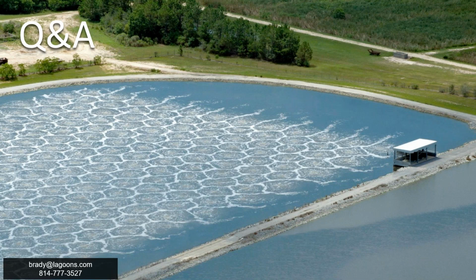Last question that has come in here, looking for a discussion on blowers versus compressors, especially with the use of fine bubble aeration lines. My experience, and we used to use compressors way back when the company started, we used to do very low airflow, and compressors were a good fit because they're relatively inexpensive for producing 4 or 5 SCFM. My experience with compressors, though, is that they're great at pressure and great at being small and inexpensive, but they're not good at volume of flow. And blowers are great at pressure and flow. The jump up from a compressor to a blower is typically a huge cost, but